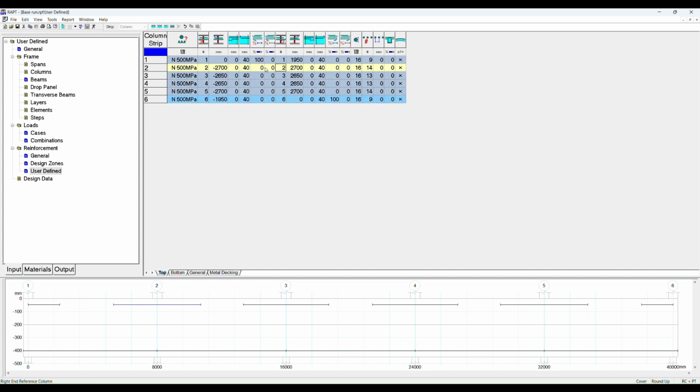Now we talk about where the bar finishes, and then how far to the right of that bar we want the bar to extend. Now, as we explained for the left-hand side, we have a bar stagger length at the left-hand side and a cover. We do the same thing for the right-hand side, similarly for development in tension and development in compression.